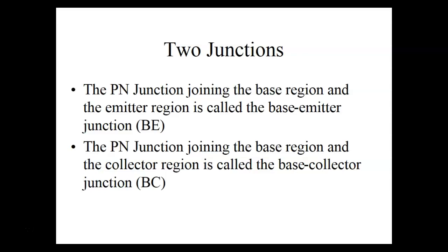And the way we make these work, we have to bias these junctions, right? You understand? So what is bias? That sounds like a good test question. In semiconductors, what is bias? Well, that's the way we would use a resistor to bias, but what is bias in semiconductors? This is a DC voltage. Yeah, these are DC voltages applied to a semiconductor.